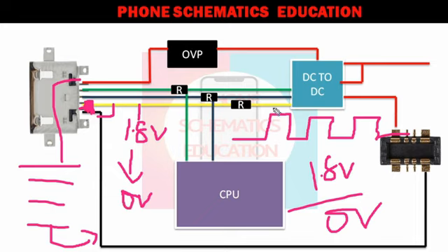Now your IC senses that before connecting any device there was a 1.8 value, and now something is connected, so the voltage on it becomes ground, or logic low. Before it was logic high, 1.8 volt, now here is 0 volt. So something is connected, mainly for OTG connections, so this IC activates the host mode. It means OTG mode.